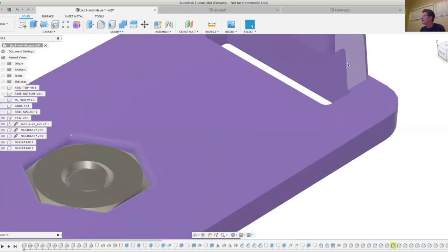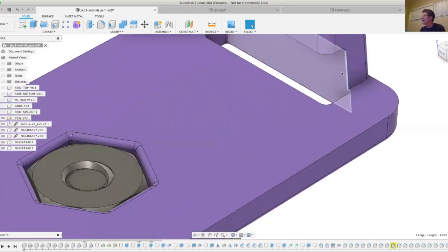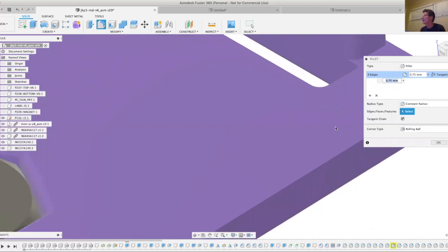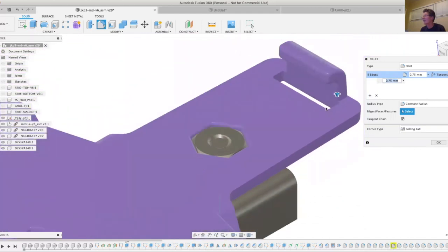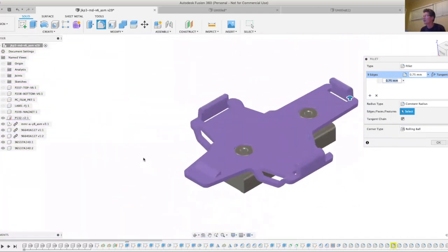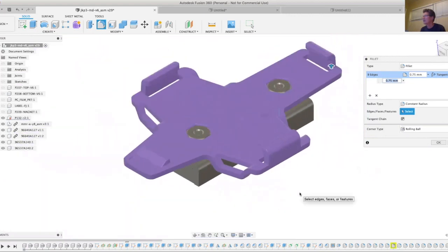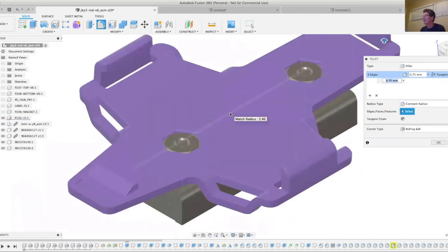I want to come over here and pick this guy right here and then create a fillet, and it's just too difficult to find it. It's just so easy to be able to zoom in and out like this. And you can kind of do it for panning even, because the zoom in and out goes on where the mouse happens to be. So that works really well.